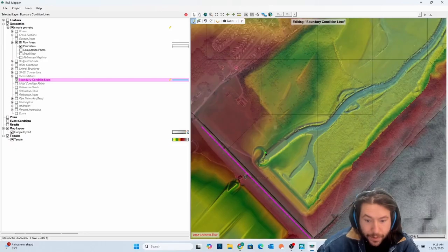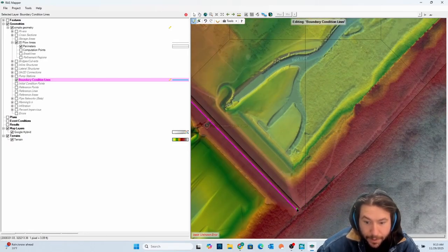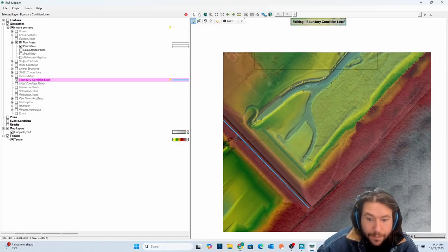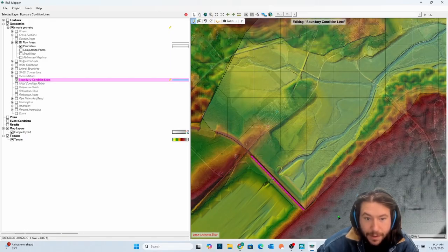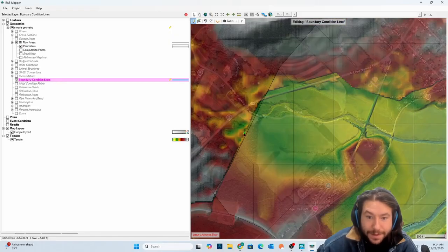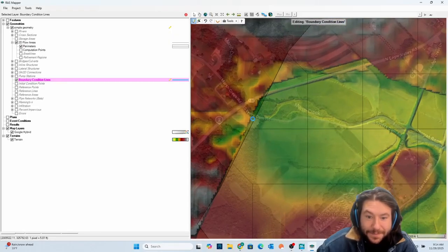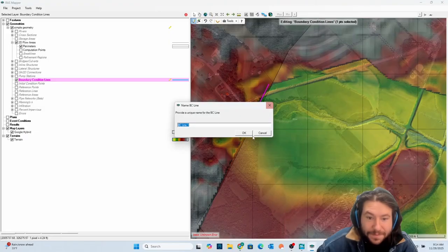So if you drew your line a little bit too far, and you see that bolded line wrapping over this edge, you want to make sure you edit your boundary condition and shrink that down, because we don't want water coming in on this edge. We just want it on this front end where we've got water flowing down from the dam. So I'm going to go ahead and continue and draw the rest of these inlet conditions along the rest of these inlets, sorry. This is Marsh Creek.